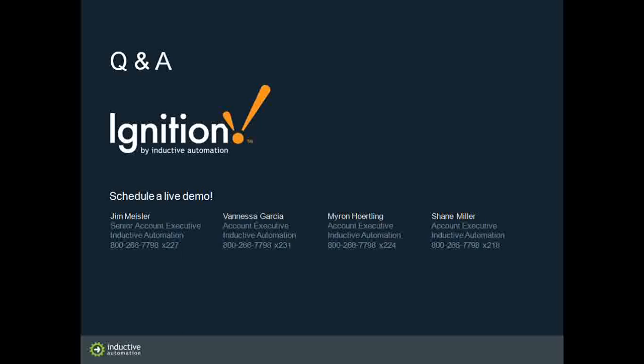What is an example of an actionable item found through implementing OEE at Diamond that was not apparent before? It's David's question. Yeah, that's a really good question because we've actually gotten a couple of good examples. What doesn't seem to be apparent in a facility like ours are the momentary pauses in our filler, and one of them is due to the scale not being tuned correctly or not cleaned properly, not being maintained as well as it could be.